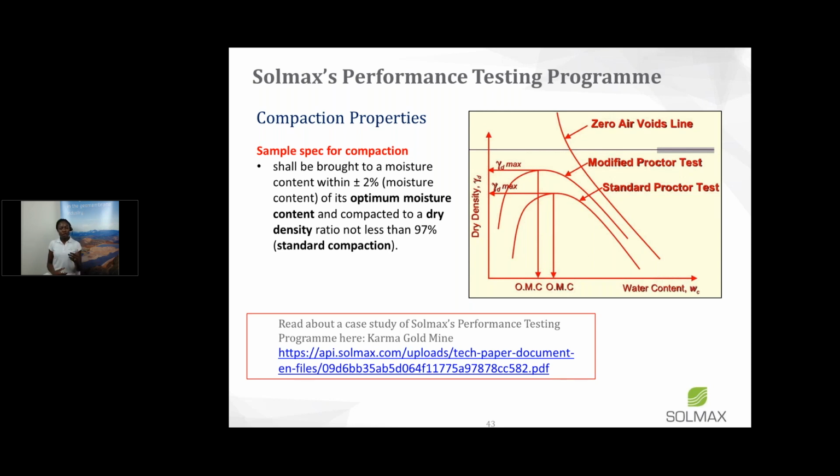Also for example, your compaction, send us the optimum moisture content, the compaction effort that we should apply, the dry density, we will compact this for you. This program has been widely successful. Engineers love it. Owners love it. We've used it on several projects. There's a good case study on our website that you can take a look at and see how it's worked for a heap leach mine project. And there are other case studies too that we can share with you if you want some more information on that.